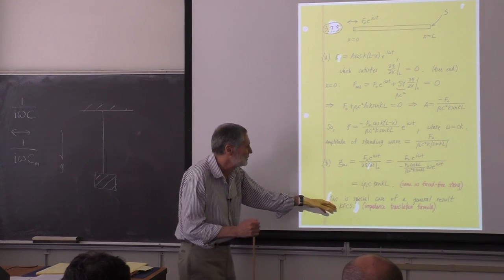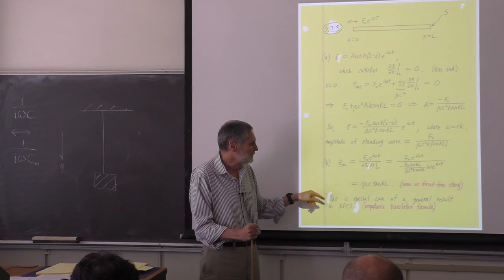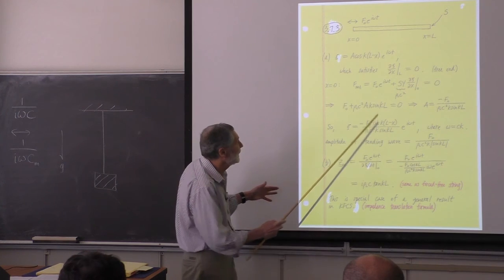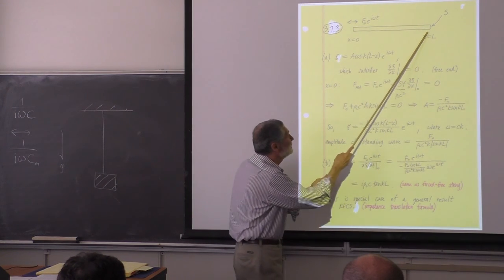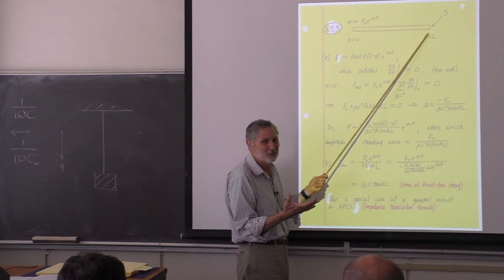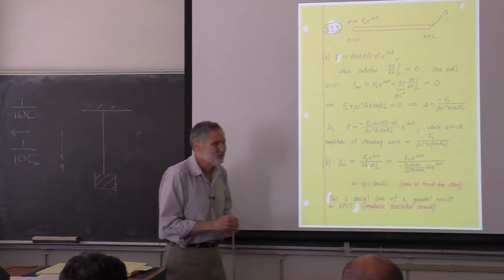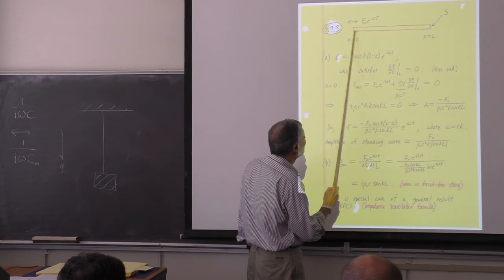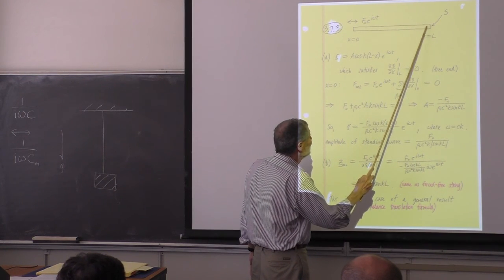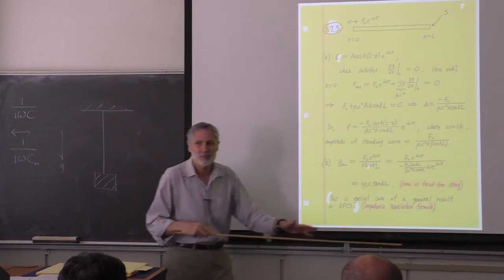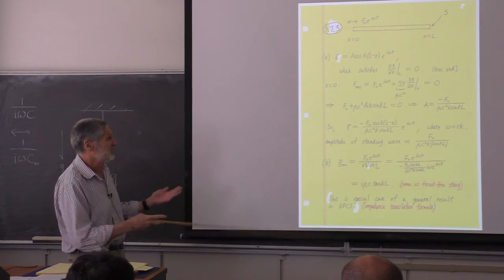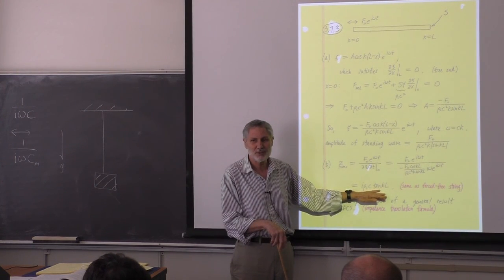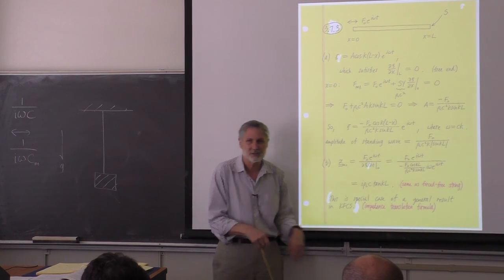And in fact, it's a special case of the impedance translation formula. Maybe some of you can see it in your head, but if you look back, what's our terminating impedance here? 0. So you just go to the impedance translation formula, which gives you the impedance seen here for any terminating impedance with a wave medium in between. And now you just set the terminating impedance equal to 0, and you'll see that you get this. That's a general way of looking at this from the impedance translation formula.